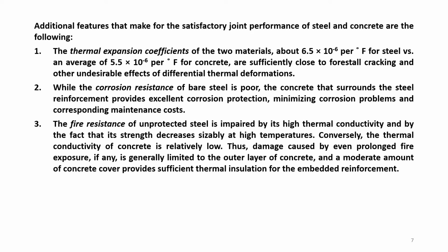This 6.5 and 5.5 expansion is very close. That's why when it is heated, the expansion of one will not be far away from the expansion of the other, or the contraction of one will not be far away from the contraction of the other. That's why they will remain altogether intact.